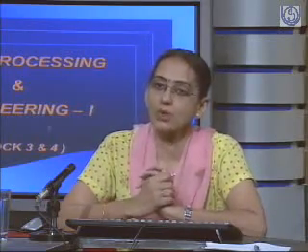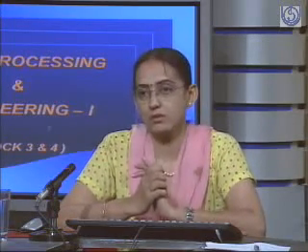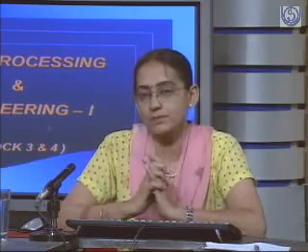The tertiary treatment is an advanced type of treatment. It is very similar to the water softening which we have seen, where the water is passed through the columns and the calcium salts are replaced with the sodium salts. So that is an advanced kind of treatment which is given to potable water. Potable water means drinking water.